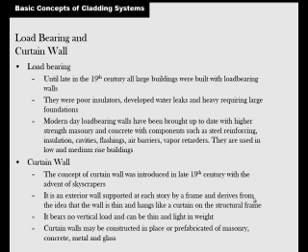And then now we have the curtain wall. This was introduced in the late 19th century with the advent of skyscrapers, like I said. It is the exterior wall supported at each story by a frame, derived from the idea that the wall is thin and hangs like a curtain. So you have your structure, that's all rigid, and then your little curtain pieces hanging on it. And that's your exterior cladding. The cladding has no vertical load. Its only job is to keep the wind and the rain out and hold on tight to the wall. But it doesn't support the building at all. If it were to fall off, the building would still be there.